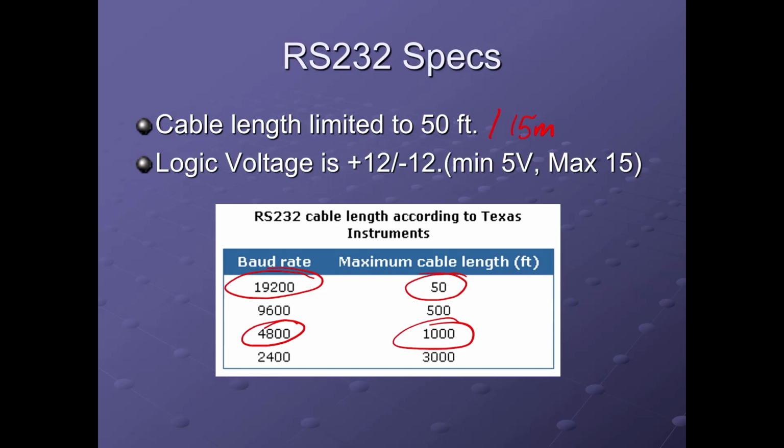But at the end of the day, I kind of give this analogy. Let's suppose you were in charge of an RS-232 node or section of your substation network, and you installed it based on the fact the order came out for 4,800 baud, and you knew you could extend to a device in the substation yard at say 500 feet away. So you're going, yeah, I'm good at 4,800 baud. But then later on, a change order comes out to change all drops within your network on RS-232 at all your substations to 19.2. Well, what's happened now, you can't just go in there and reprogram that connection to 19.2 and expect it to work, because you strung those drops to 500 feet.